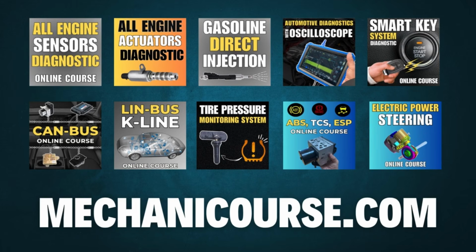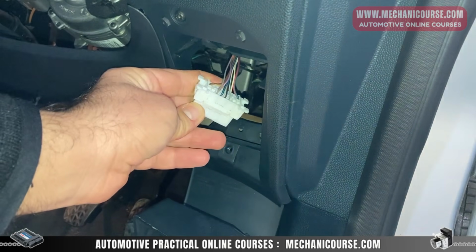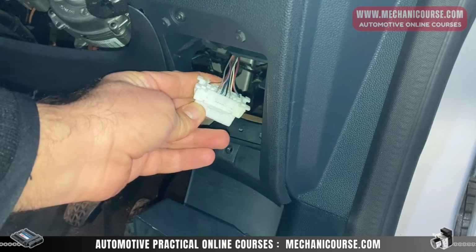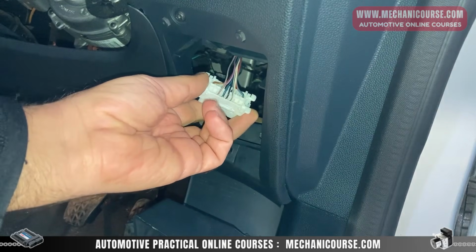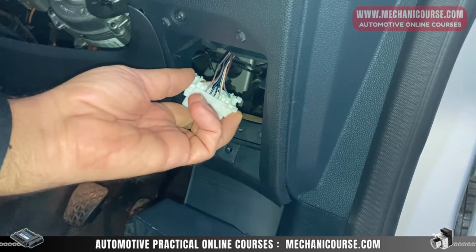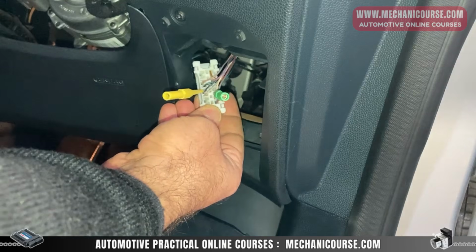Now let's start. Here's the OBD2 connector. You know that we have two pins on the OBD2 connector, pin number 6 and 14 for CAN bus high and low. You can actually reach the CAN bus high and low from here and perform the diagnostic. So what I will do, I'm going to back probe the CAN bus high and low. So we have the test probes inserted.